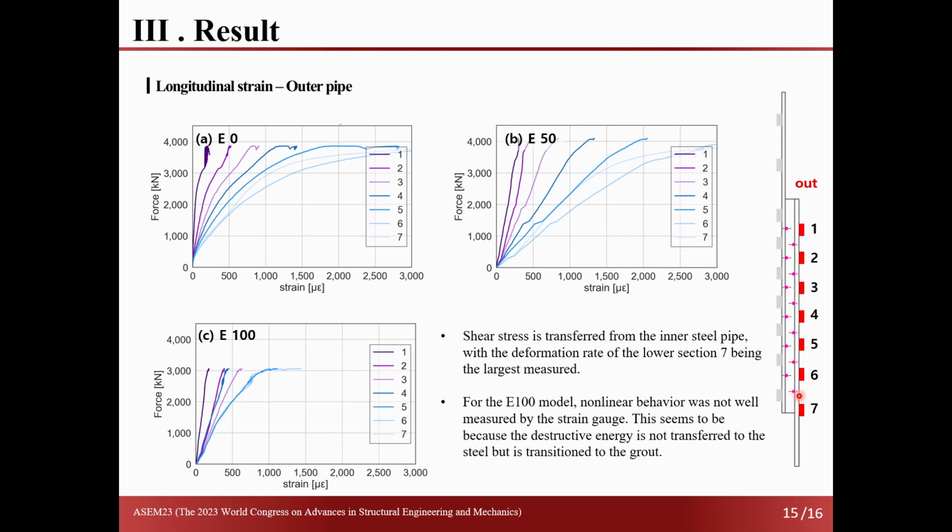For the E100 model, linear behavior was not well measured by the strain gauge. This seemed to be because the destruction energy is not transferred to the steel, but transferred to the grout.